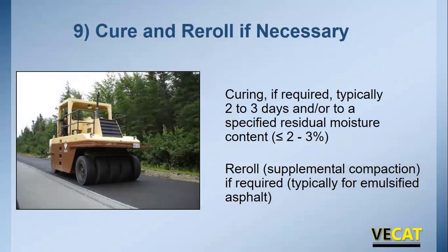Another thing we can do, we want this mix to cure out before we put the surface mix on top of it, and it does require a surface mix due to the high air voids. So we typically like to see 2 to 3 days worth of traffic on it before we cover it up, and we like to see that residual moisture content drop below about 2 to 3%.